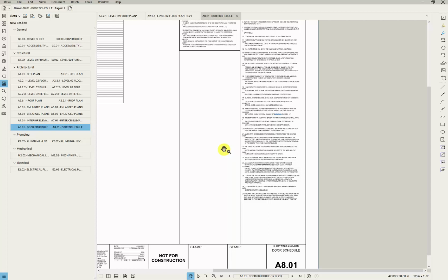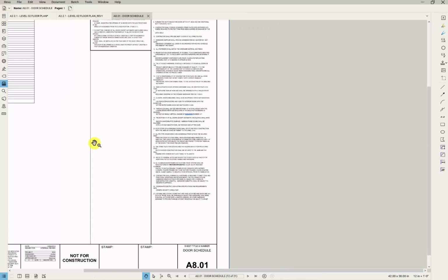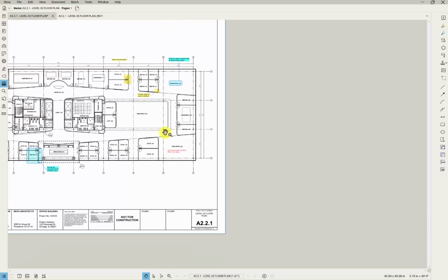Now we're going to look at, when you're doing this organization, what happens when things change? There are two ways Bluebeam does this in Revu. One is through Compare Documents, which highlights each of the changes with a cloud markup, and that exists within the markup list. Or it does it with Overlay Pages, which is simply overlaying the two pages, and through the colors you'll be able to see. So let's go back here.